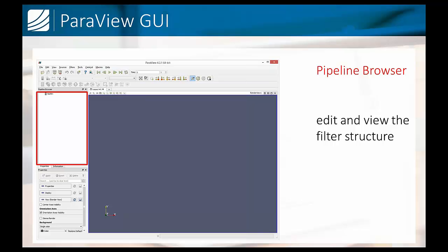With the online post-processor, can you probe a model to find the stress at a specific point? Yes, you can do that. There is a particular filter called probe location or plot over line. With that, you can visualize the results at particular points or along the probe line that is being posted there. But getting back to the ParaView graphical interface, I'll also show this probing tool in the offline post-processor.